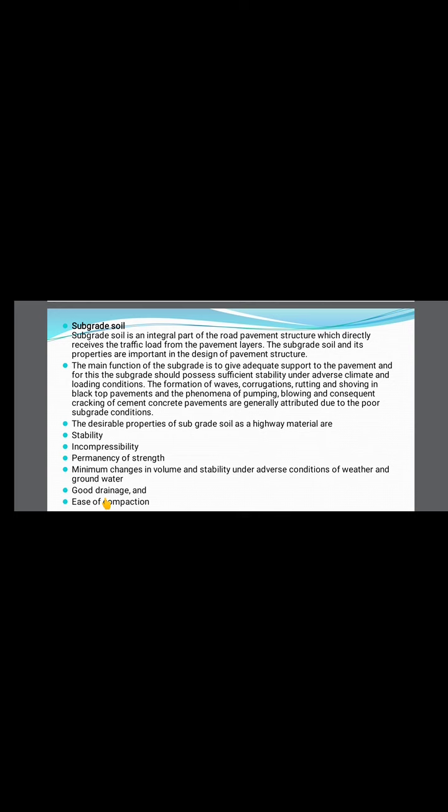There are various desirable properties of subgrade soil for highway materials listed here. One is the stability of the subgrade and incompressibility, permanency of strength, minimum changes in volume and stability under adverse conditions of weather and groundwater, good drainage, and ease of compaction.